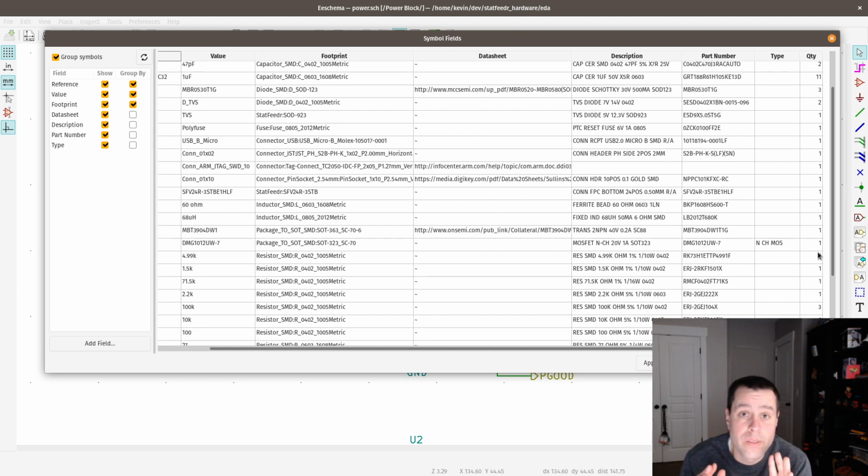So that resistor is a unique part that I have to pick a part number for, like this part number right here. I have to come up with that and make sure that it's stocked and follow the stock. So the more unique parts you have in your bill of materials, the harder it is to maintain, because you're tracking end of life for components and making sure that everything is in stock and supplied and all that.